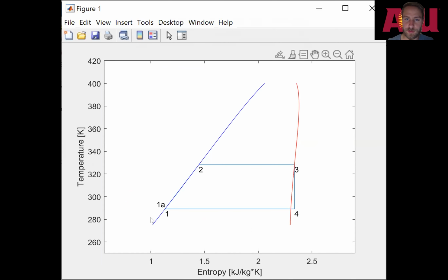So this is for isobutane. It shows that there's very little pump work compared to the whole system. It also shows right here that because this is over the vaporization curve, we would need a dry fluid pump for the system, which could be pricey. Good things to know if we were to further develop the prototype.